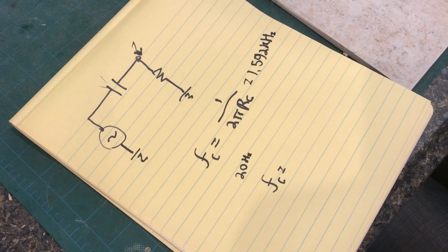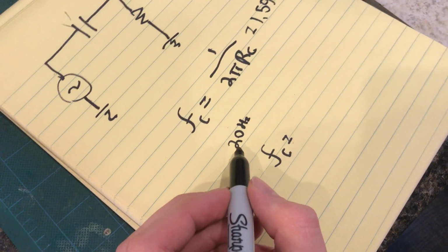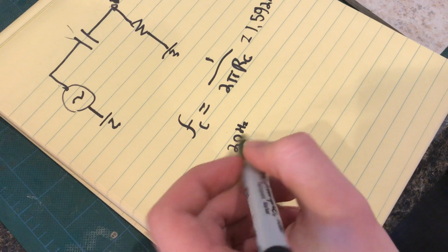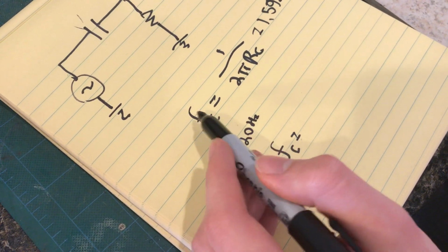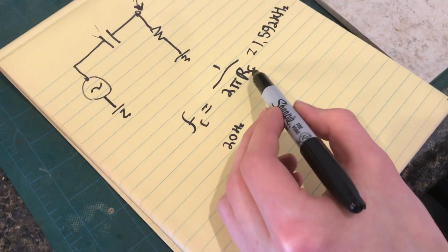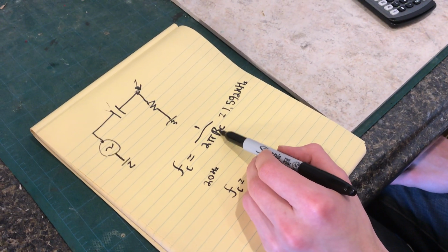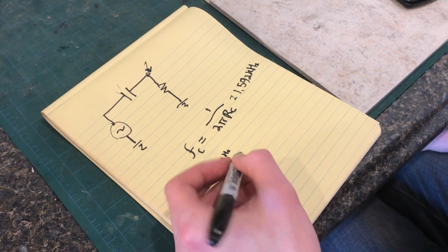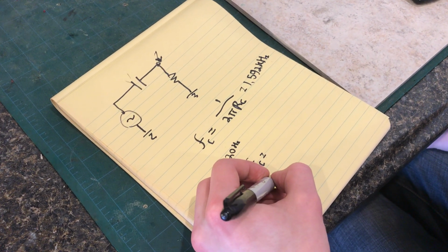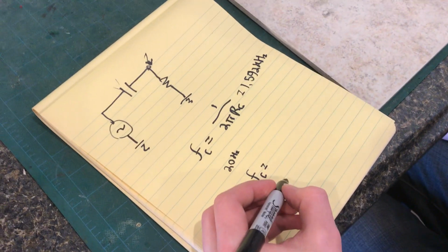And we want to do a high pass filter on this and cut out everything below 20 hertz. So in this case, we would rearrange the equation for whichever value you were going to be changing. I'd say probably R, as I have a bunch of resistors.